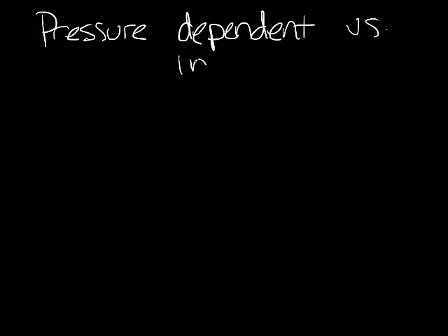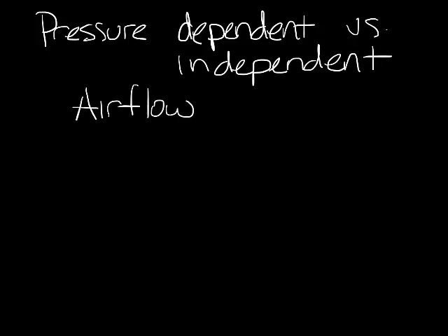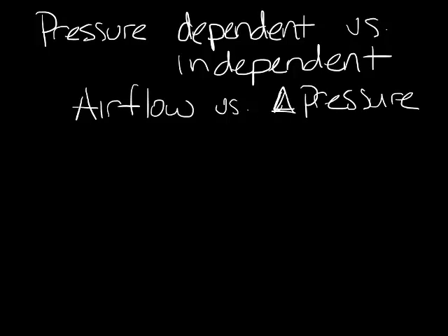I'm Jenny Civey, and today we're going to follow up on last week's pressure overview with what's the difference between pressure dependent and pressure independent VAV boxes. Pressure dependence and pressure independence has to do with how airflow through a VAV box reacts to changes in pressures in the system. As the name implies, the amount of airflow you get in a pressure dependent box depends on how much pressure you have. So what does this mean exactly?